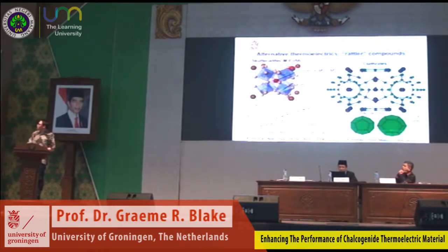A similar process occurs in the clathrate group of materials that's shown on the right there, for example, Ba8Ga16Si30. Again, all cheap materials. ZTs of approaching 1 have been achieved here. And here again, the barium cations are enclosed in large cages in the crystal structure, and they're able to have large thermal vibrations and rattle around.